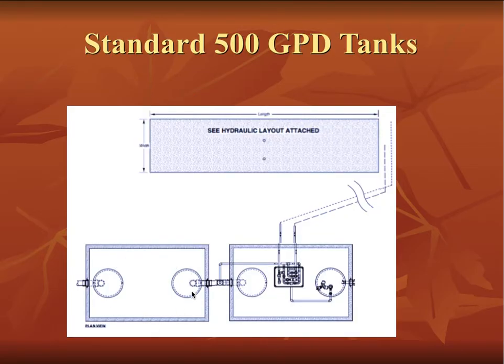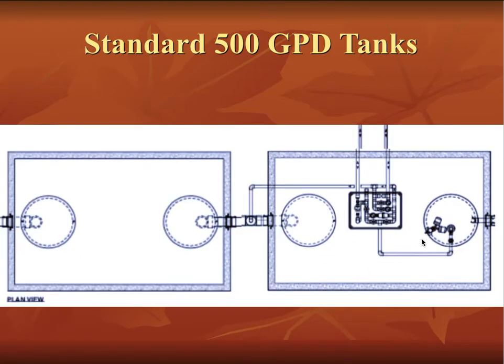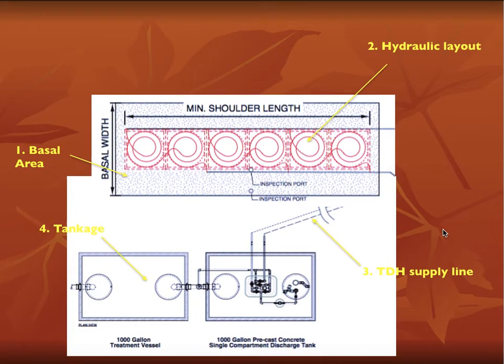Here's an overview. First tank spills over to the second tank, our spec'd out headworks, going out to your drain field. Inside, you have a pump and 2 floats. Here's a closer look. Pump and 2 floats. And the total area, again, just walking through everything. Here's your tankage. So here's where your pre-treatment unit would be. If you're using septic tank effluent, then this is just a settling tank. Our pump tank, pump, 2 floats, going out to our headworks, and then out to the coils.